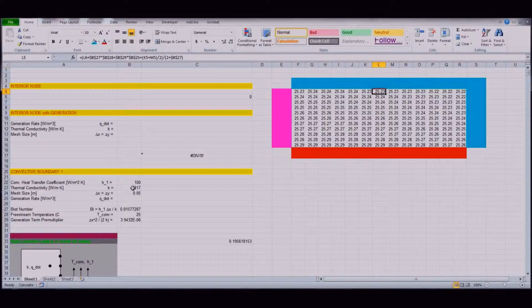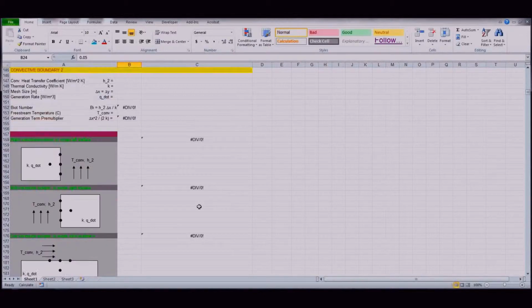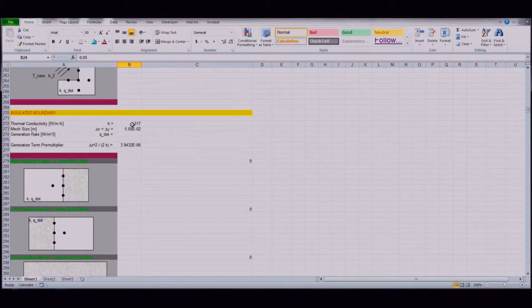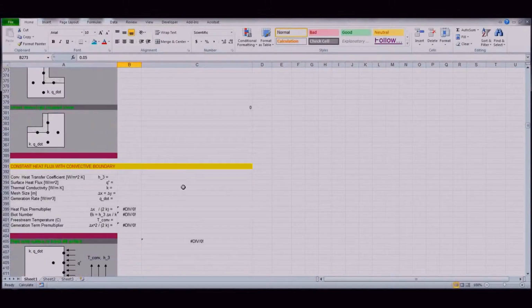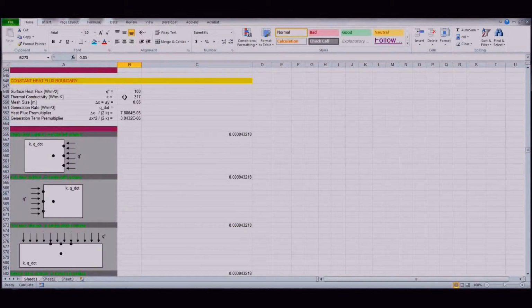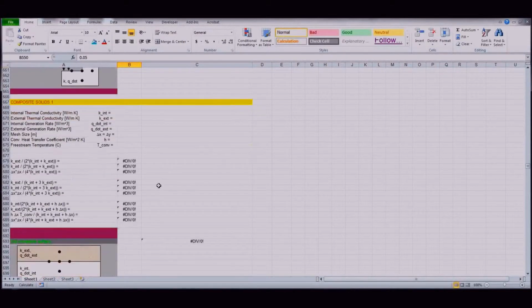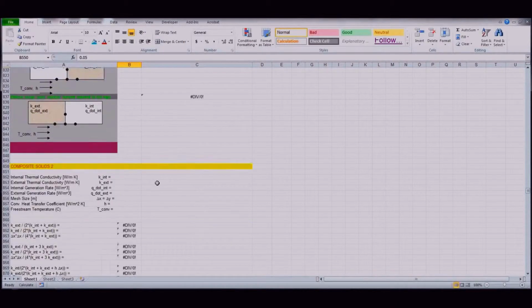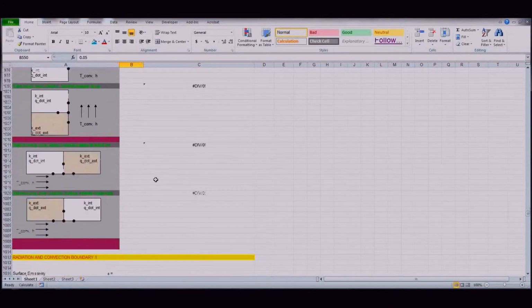What I'm going to do, I'm going to drop the thermal conductivity in all of the boundary conditions that we've assigned. Let's drop it down to 100. So we'll change that, and then let's look for all the other ones. There's one, 100. Maybe that's why heat transfer textbooks rarely use gold. There's heat flux was 100 watts per square meter. We'll put 100 there. And let's see, were there any other boundaries that we used? No, I think those were all of them.